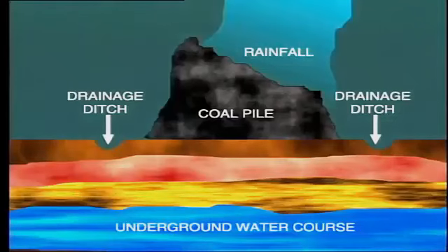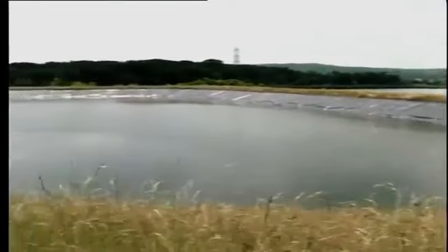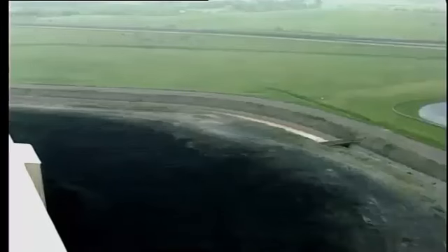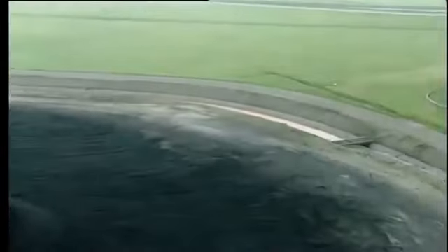rainwater down through coal piles or ash piles. This water, taking with it contaminants, some of which may be hazardous, percolates down through the earth. There it may find its way into the natural groundwater, which is often used for drinking by animals and people. Nowadays, it is necessary to install an impervious liner, usually of heavy plastic, below any of these areas, including the ash pond. Stormwater runoff must be collected and treated to remove solids. A liner is also required for the landfill area where solid waste is eventually laid to rest.